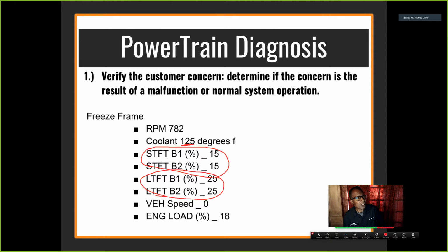So to diagnose this, this would be like an intake manifold gasket leak. One of them plastic intakes that leaks when it's cold but looks normal when it's hot. For example, let's say they give you these numbers right here. Say at 159, that's when it's definitely in closed loop. My short term goes to 5, and my long term goes to 2.